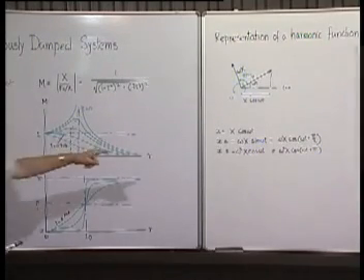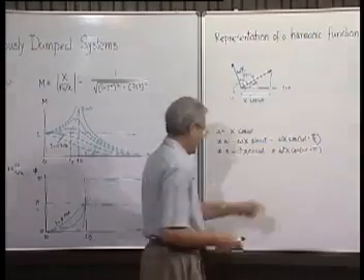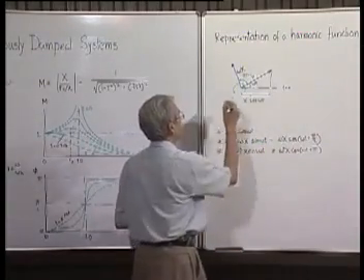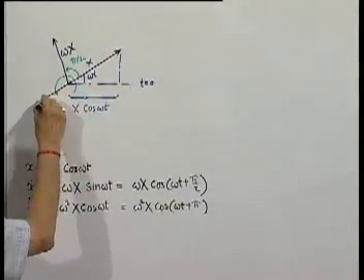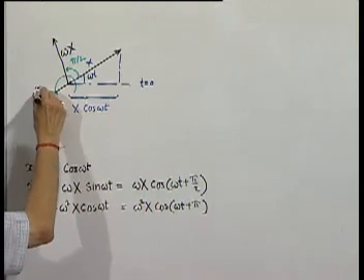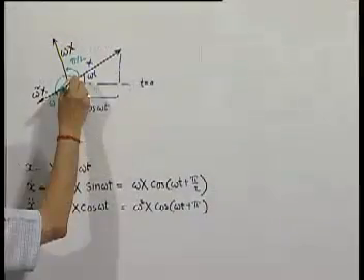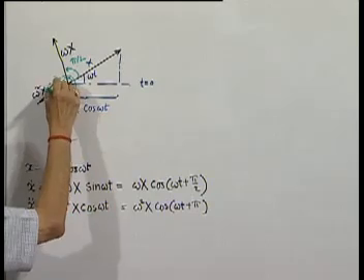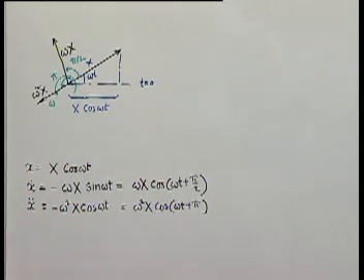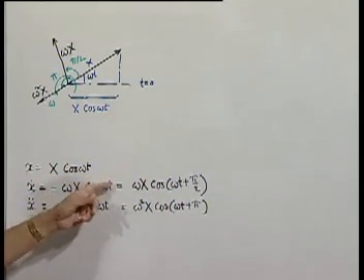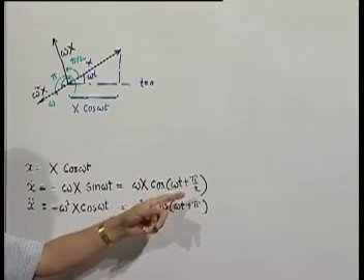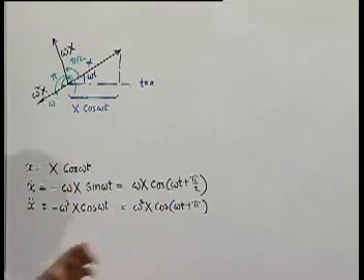So this is again a harmonic function of time, and can be represented by a vector whose magnitude is omega square x, and that is leading the position vector by 180 degrees. As can be seen, this is leading cosine omega t by 90 degrees, and this is leading cosine omega t by 180 degrees. Fine, so you can also keep on doing it.